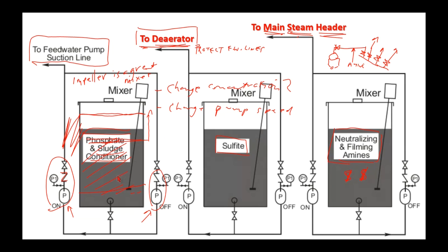Well, how much extra chemical do you add? And does it make sense to increase the concentration of the chemical in the whole tank when maybe that amount of chemical won't be necessary to actually adjust the phosphate in the boiler? So I think that's kind of where you're going with that, right? It's kind of inaccurate and it's kind of sloppy.